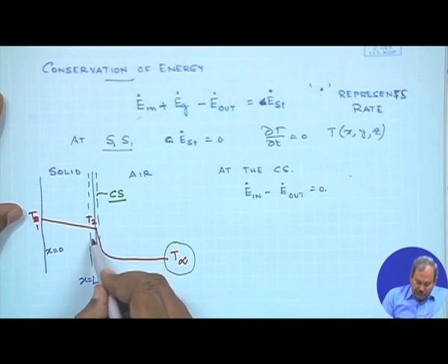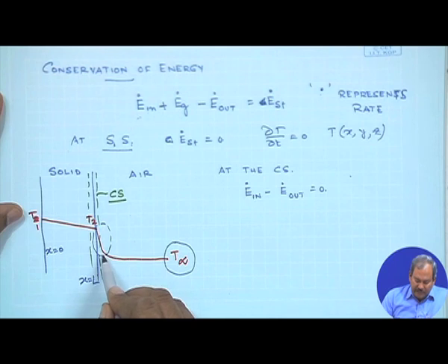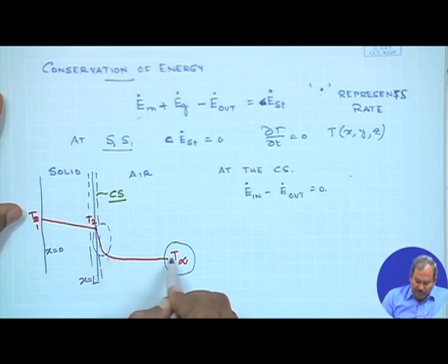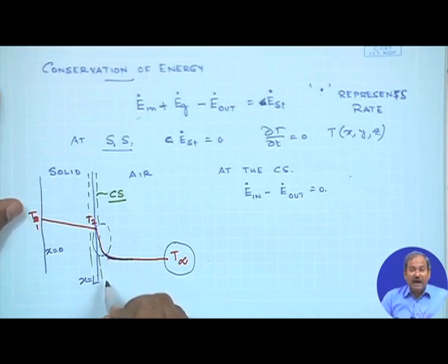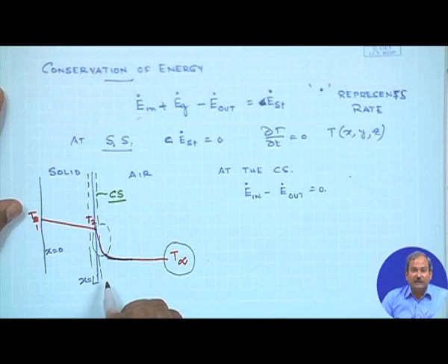So, if you consider this region, which is very close to the solid surface in the fluid, where the temperature sharply changes from T2 to that of T infinity far from the plate, you see that the temperature asymptotically approaches the free stream temperature. So this, by analogy with our previous discussion, you can clearly see essentially establishes the concept of a thermal boundary layer.